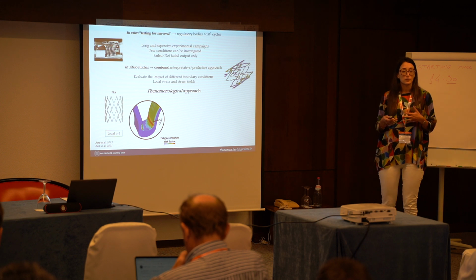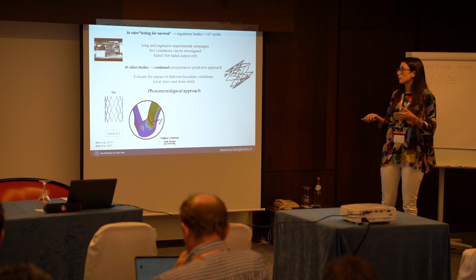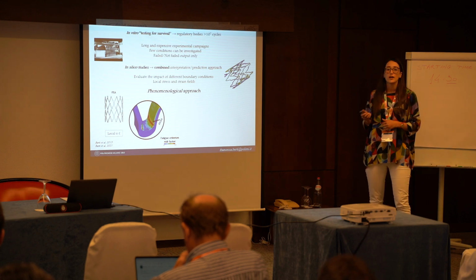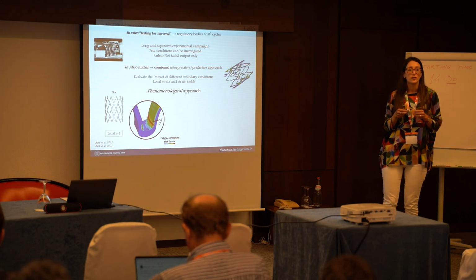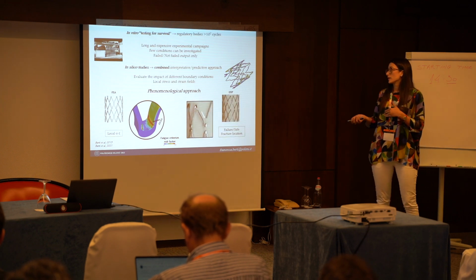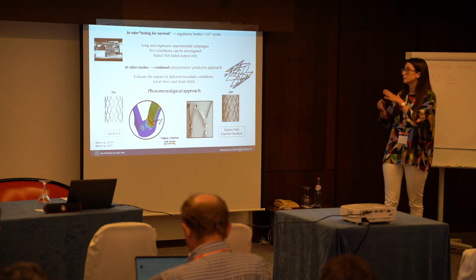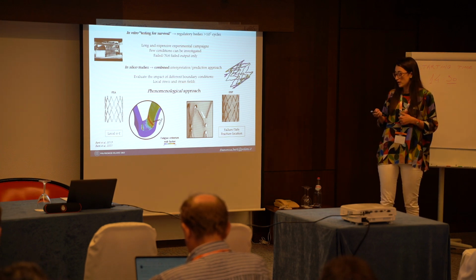I simulated different boundary conditions, I extracted stresses and strains, and through proper fatigue criteria, I tried to investigate which was the most critical zone of the stent. Then I performed experimental campaigns in order to validate my results. That is a macroscopic approach.